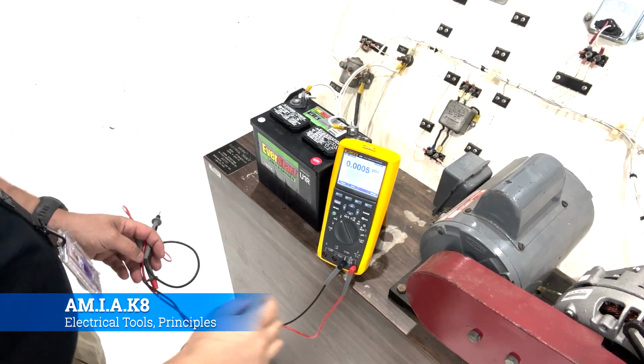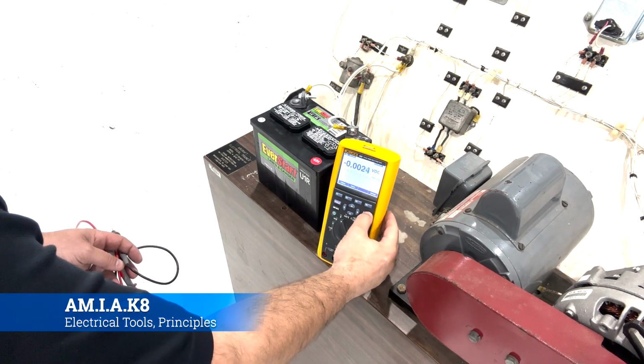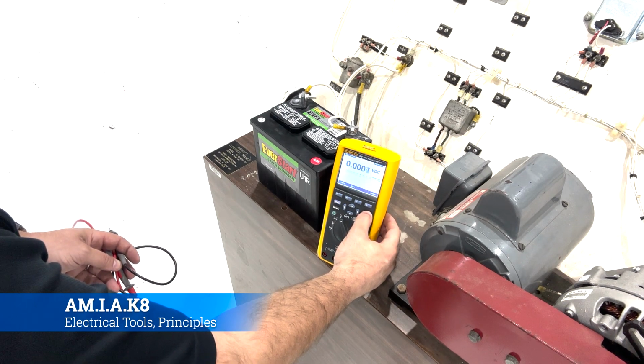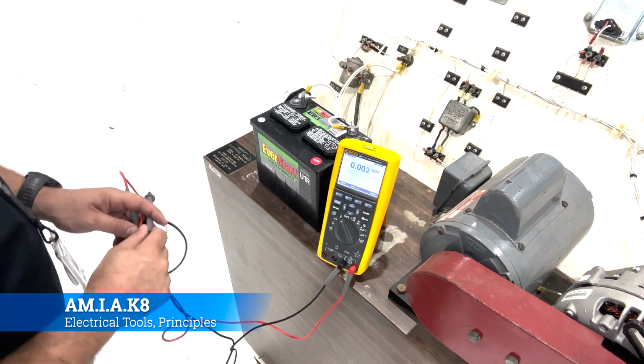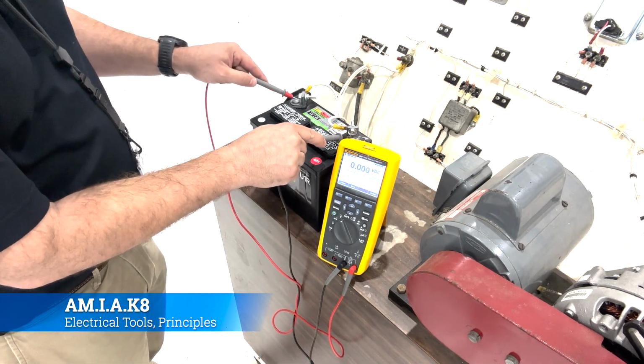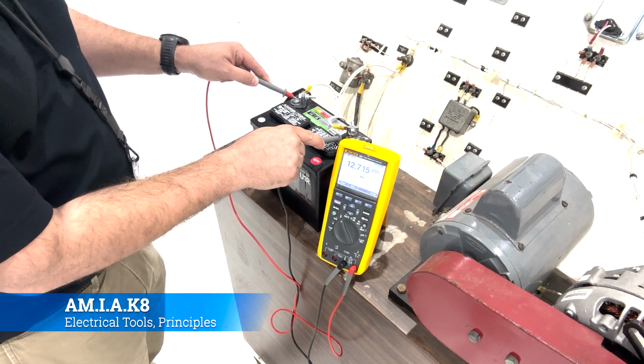Another pretty common use for the multimeter is to actually use it for voltage. So here we're going to test the battery for DC voltage. We're going to see if it's charged or not. If it's charged, it should be over 12 volts, and so we're going to take our negative lead, put the negative on the negative, positive on the positive, and we see we get 12.715 volts in the battery.